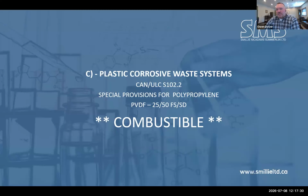So this leads us into C of the A, B, and C that I talked about in 2281 or 7281. So the plastic corrosive waste systems are again under the CSA B181.3. And because they're plastics used in non-combustible construction, they also have to comply with either the flame spread, or the flame and the smoke if it's being used in a plenum. So plastics are all classified as combustible. As I mentioned, if you have a corrosive waste application in a vertical shaft, there's no other option.